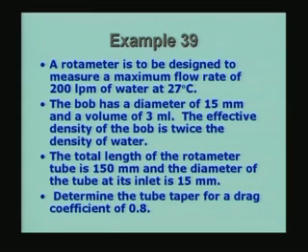That will be the maximum level possible in this particular case. And the diameter of the tube at inlet is also equal to 15 mm. So, the bulb will be just sitting closing the opening at the bottom, and as soon as you start the flow, it will float up. When the flow is taking place, it will float up, and it will take a position which corresponds to the volumetric flow rate which we are measuring.